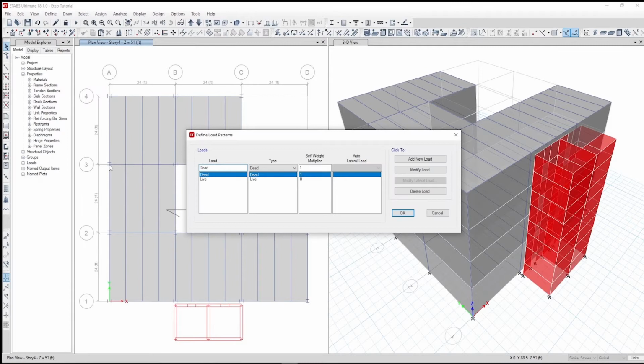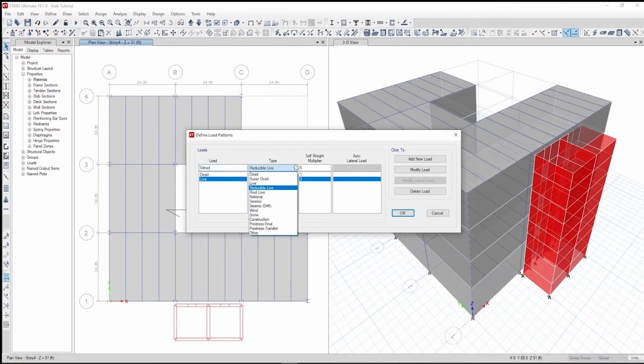The static loads used in this example consist of the dead, live, earthquake and wind loads acting on the building. An unlimited number of load patterns can be defined. This example also applies an ASCE 7-10 static earthquake load to the building and an ASCE 7-10 wind load to the building. The forces that are applied to the building to account for the earthquake and wind load are automatically calculated by the program. Note that there are two default load patterns defined.